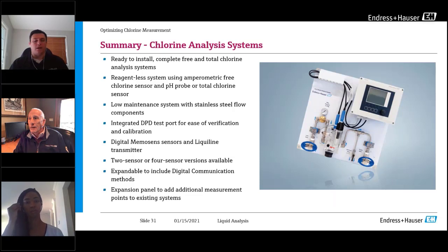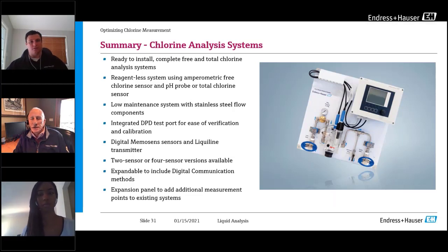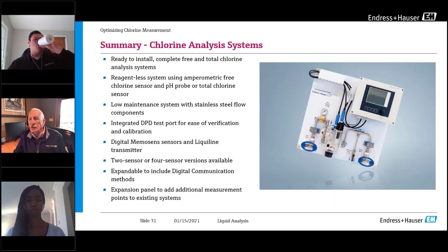I mean, at least I don't know of different pH values for the DPD test kits. I think ours is just kind of set. Is it 6.8 or is it 7.6? No, it is the pH value that DPD tests are standardized to. Generally speaking, with a buffer, it is roughly 6.3, 6.5, somewhere in that general area. So that's kind of the magic pH number.